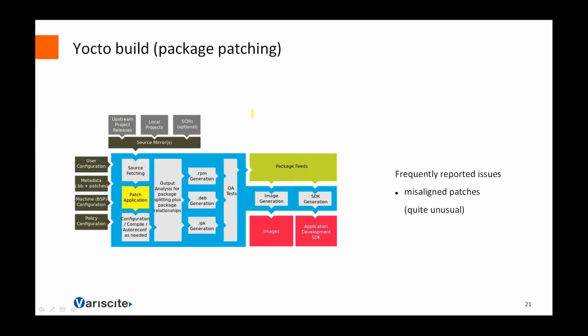you will pass to the patch phase. Why do we need to patch software that we have just downloaded? Mainly because sometimes the software, officially as is, is not suitable for embedded builds. Sometimes it may need some patches to be more general. Sometimes they need patches to extend capability.